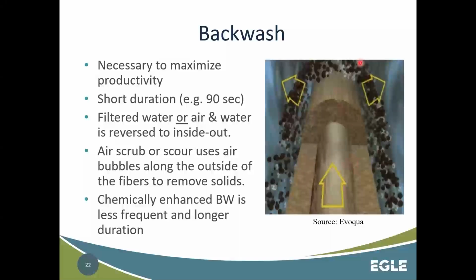And as you can imagine, as this gets dirtier and dirtier and plugs up more and more, you're going to have a higher transmembrane pressure. So the difference between here and here is going to increase with time. When you do this backwash, that's going to help restore and bring your transmembrane pressure back where you want it, but it's not going to take it all the way back to original.